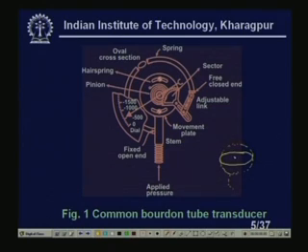It is elliptical initially, and now it tries to become circular. The tip of this Bourdon tube is a free closed end. The pressure comes in here, goes through and hits this oval or elliptic cross section. Then this will move up. If this tip moves out, then the sector, we have a sector here, moves in this direction.